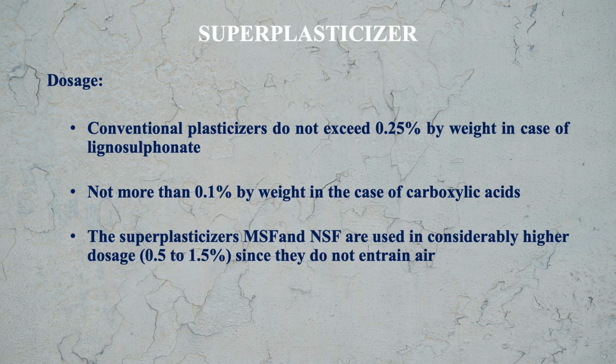The superplasticizers MSF and NSF are used in considerably higher doses, that is 0.5 to 1.5%, since they do not entrain air.